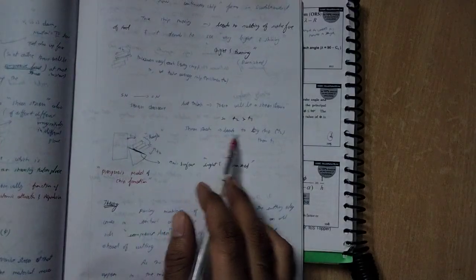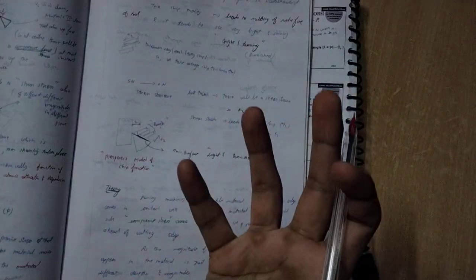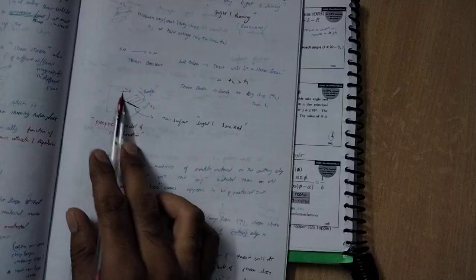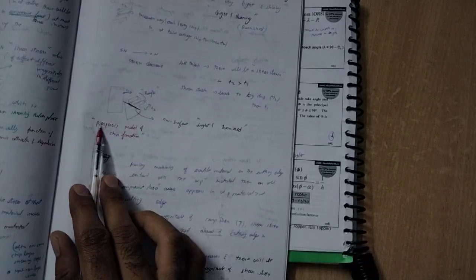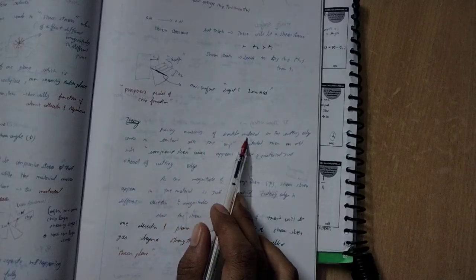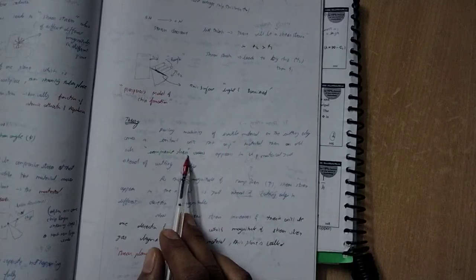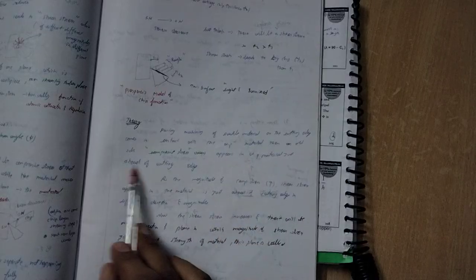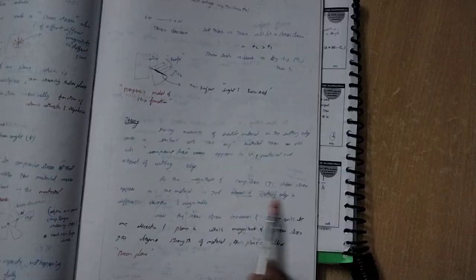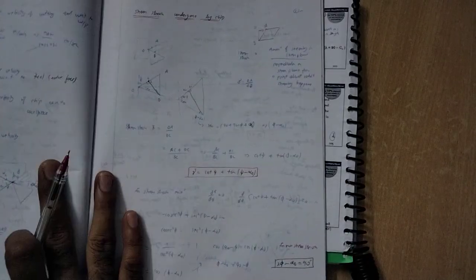Due to the shear strain, the chip tends to become thicker; it expands a little bit due to the shear strain. You can see while it is moving, it is bright and plain. So this is the previous model of chip formation. During machining of a ductile material, when the cutting edge comes in contact with the workpiece, compressive stress is generated in the material just ahead of the cutting edge. As the magnitude of the compressive stress increases, shear stress appears in the material just ahead of the cutting edge, and this entirely goes into a shear plane. That's it.